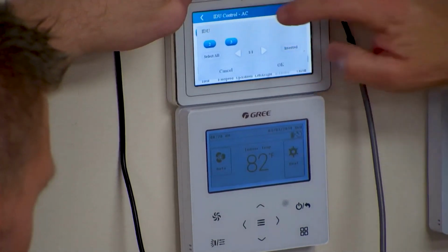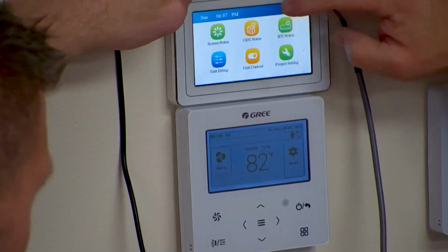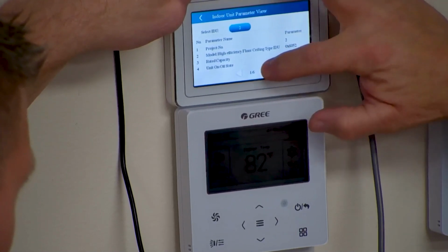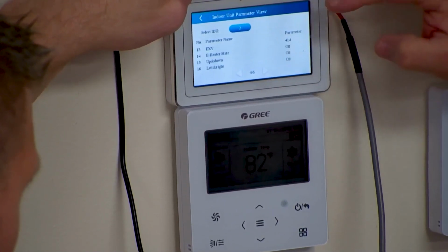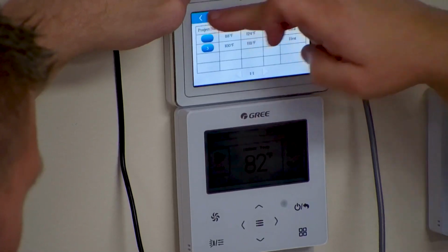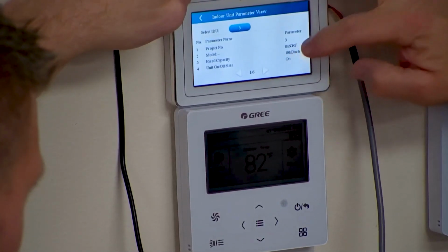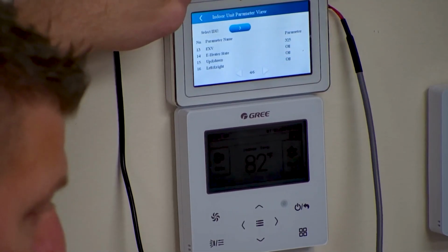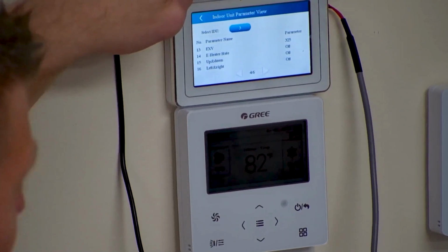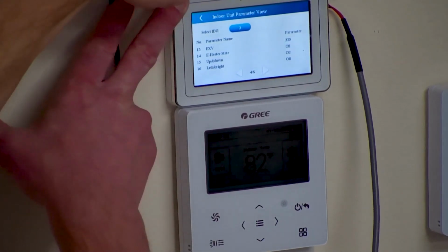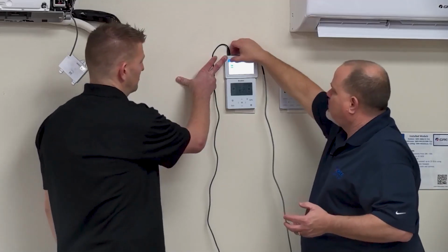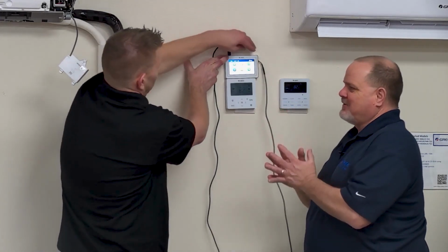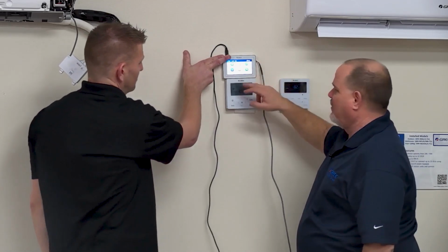Hold on. I'm trying to go through it too fast. All right, so I'm going to that status view of indoor unit. This one's at 414. Unit number 3 is at 325. So that's right where it was. Yeah, it's close. And it doesn't need to be exact. What I'm telling you guys is for troubleshooting purposes, you don't need to be that perfect. All we want to know is, is that EEV wide open? Is it not wide open?